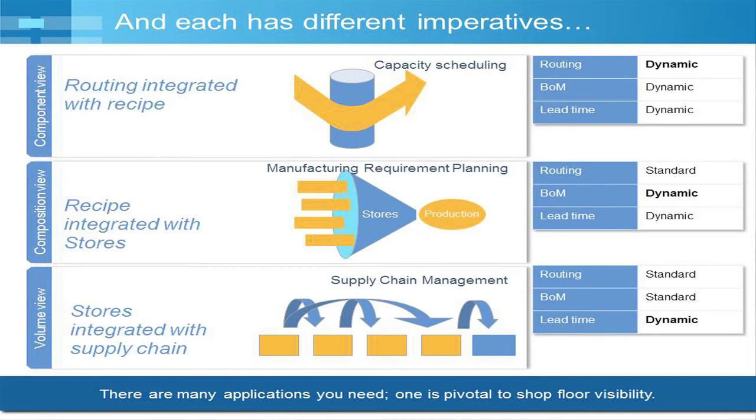Now finally, when your routing, that is your operations, are dynamic, which particularly happens in an engineer-to-order situation, what you actually look for is a capacity planning system where you see which machines can be applied at what idle time. So you require a capacity planning system so that you can have a more dynamic routing system. You can make the system look for idle times from the calendar of every machine and allocate operations in those machines based on every order that you get.